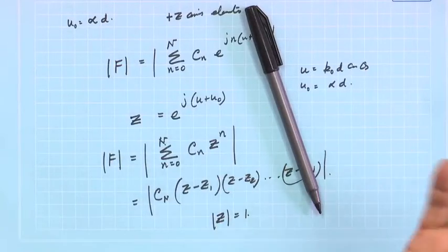If you remember the Butterworth polynomial, an nth order Butterworth polynomial has n plus 1 zeros, and there it becomes maximally flatter and flatter. These zeros are nothing but nulls of the array pattern. So, if I want a maximally flat type of pattern, then we put more and more zeros.